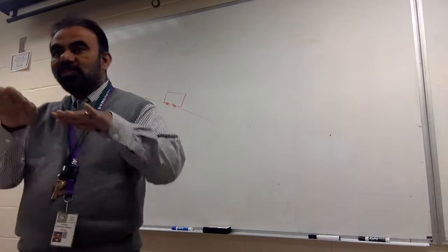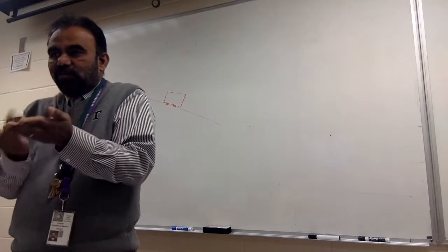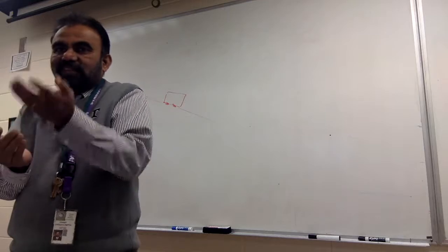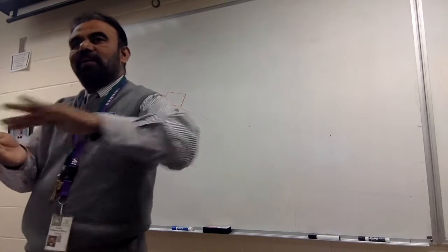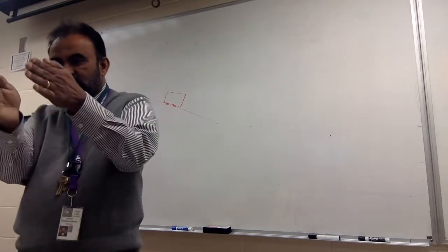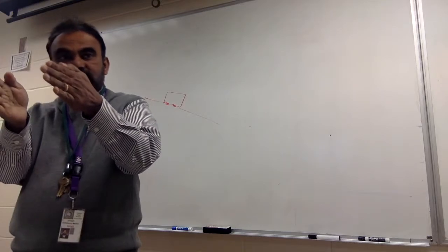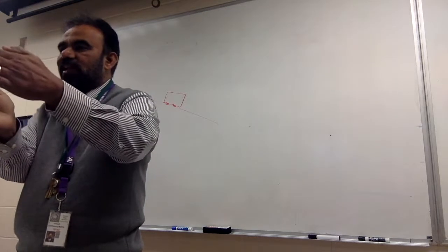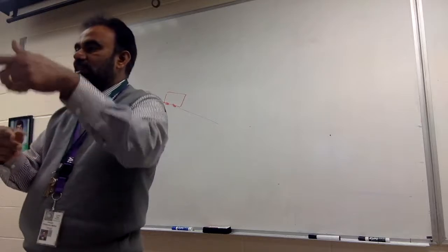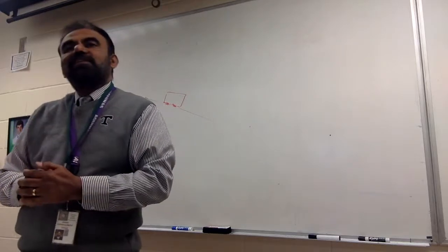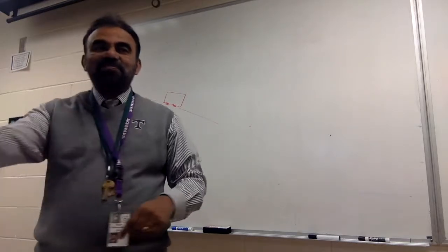So then we had to tilt the tracks. We removed the nails a bit, put some packing under the tracks there, and made the tracks leveled differently. So we raised the track in such a way that the outer track was slightly higher than the inner track. And then we made it run. It beautifully took the turn.